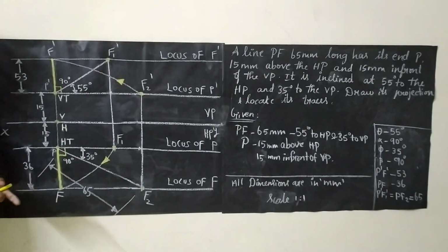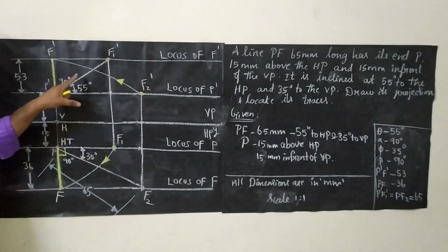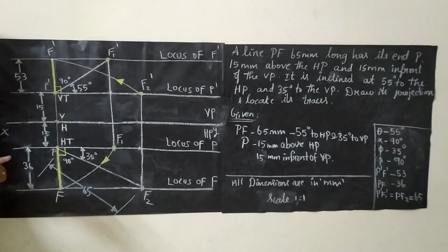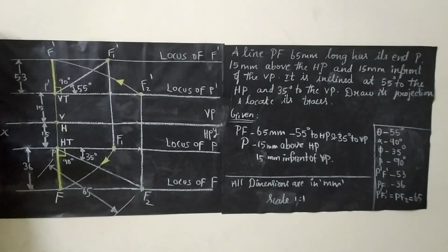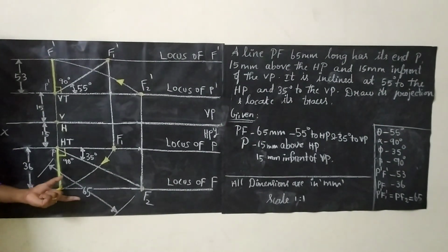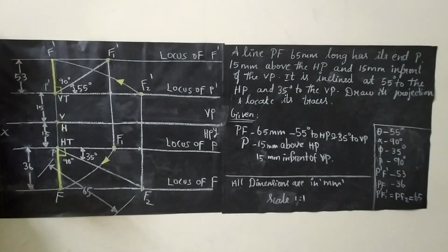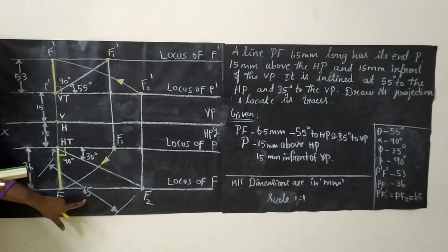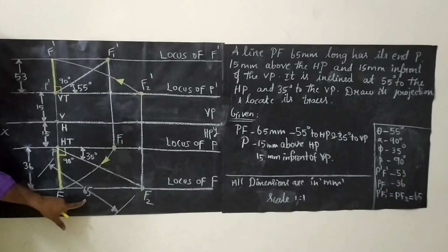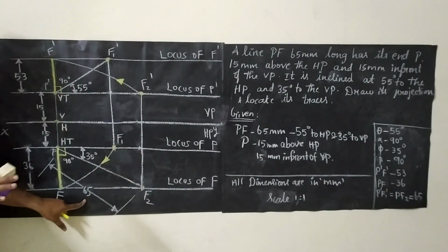One thing I just forgot to tell: you have to dimension your true length, because we are having two sides, true length on both top and bottom, right? Try to dimension the true length on any one side. So I have taken the bottom side and I have dimensioned it. This is the extension line. Extension line should be perpendicular to the PF2 line, and dimension line can be drawn with your H pencil. Extension line can be drawn with your 2H pencil. Now write the number, whatever number you are getting, in HB pencil vertically.